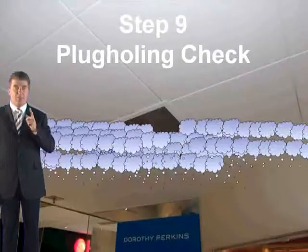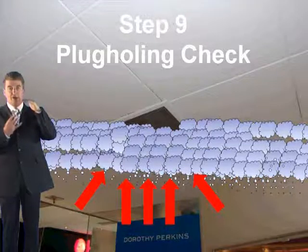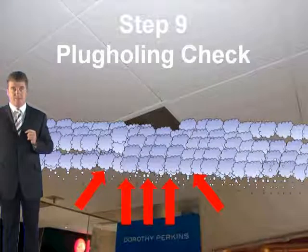Now we need to move on to step 9. You've got to carry out the plug holing check. You've got to make sure that the smoke will not plug hole and cause a vortex which will induce air and affect the efficiency. Now you do this for both natural and mechanical ventilation. Don't forget there's two models which determine if plug holing is likely to happen, and it depends where the ventilator is. If the ventilator is less than 2 metres away from the edge of a wall, you use one model, and if it isn't, you use the second model.